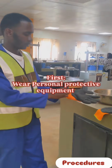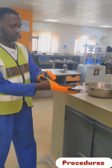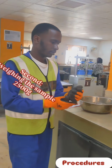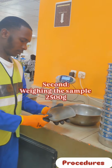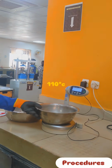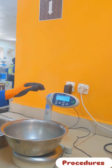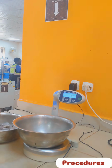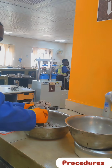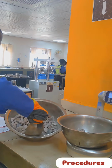Firstly, wear the recommended personal protective equipment to protect your body from contaminants and harm. The second, weighing the sample. Before weighing the aggregate sample, ensure it is oven dried at 110 degrees Celsius to a constant mass according to standards. The required mass depends on your maximum aggregate size. For our coarse aggregates, we weigh out exactly 2,500 grams of dry material.